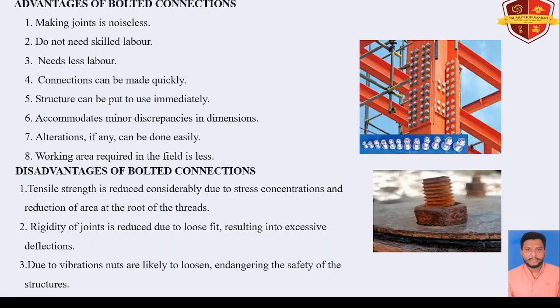Then what are the drawbacks of bolted connection? Tensile strength is reduced considerably due to stress concentration and reduction of area at the root of the thread. Due to vibrations, the nuts may be loosened. It will affect the strength of the structures.